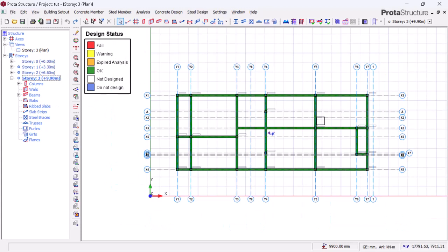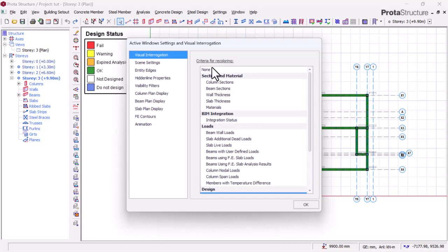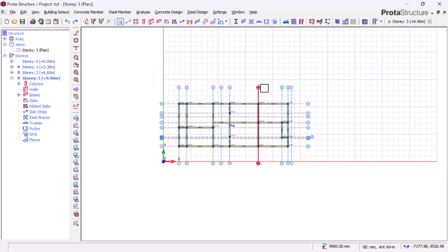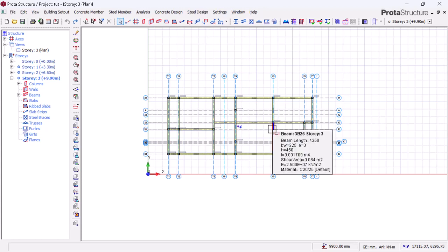With this design, you can rest assured that you've done a great job modeling a two-story building, with your arms on your chest, that this is a good structural analysis. So it's a good one. We can still go back to our visual option, the design, and say none. Then go back to your plan view. You can see now that you've run all your analysis successfully and everything has run okay, your design is okay.